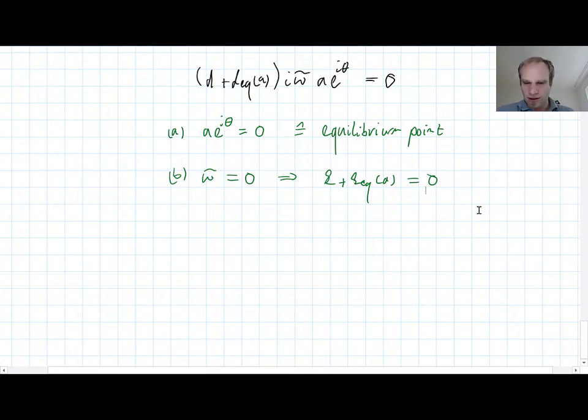What does that mean physically? If stiffness goes to 0 under variation of some parameter, this means that we have a transition from a statically stable to an unstable equilibrium position, right? If we actually have a 0 crossing of this term here, this would mean that for a certain amplitude we have a transition from static stable to unstable static equilibrium point. Okay, that is a possibility.